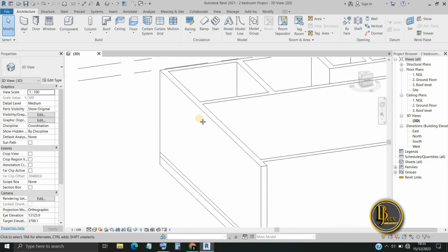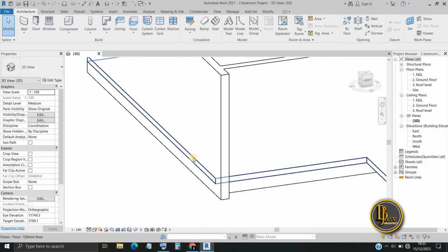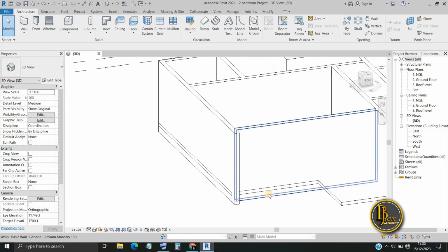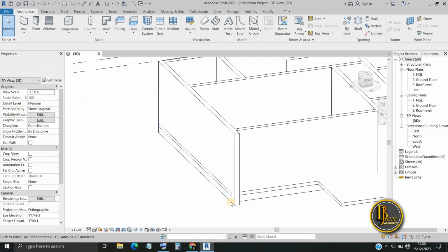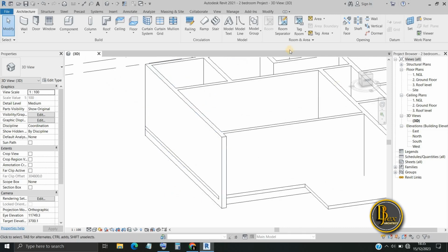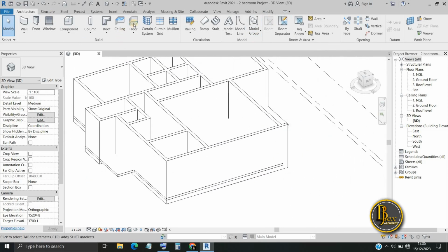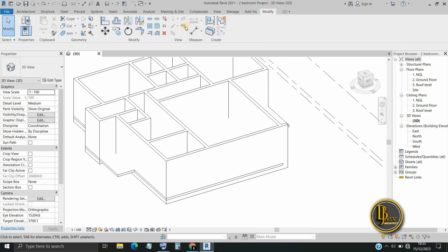The floor we drew is coming outside of the wall, is showing outside of the wall. There is a fix to this, but the fix, like I told you, if you use detail lines, they are view specific. Let's say for example, I'm trying to fix these lines that we are seeing here. If I go to this ribbon we have there, where you have the architecture, structure, steel, precast and all that, if you go to your modify, you will see something like line works.